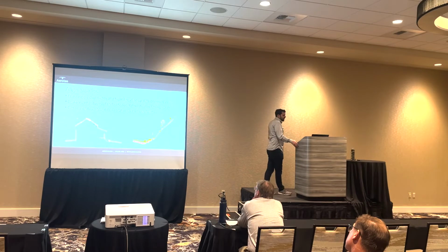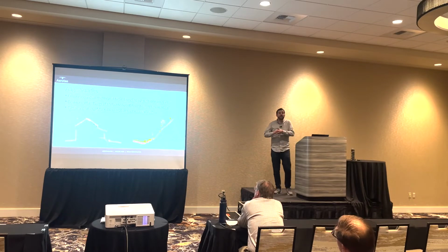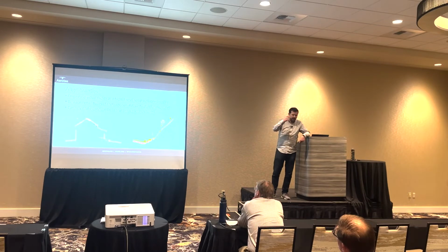To do this, there are a couple ways you can actually line things up. You can rely on post-processed data, IMU. You can get OPUS solutions if you have any ground data, or if you have the GPS data for the base station that you used while flying the drone. That's actually our preferred workflow when we fly with the L1.